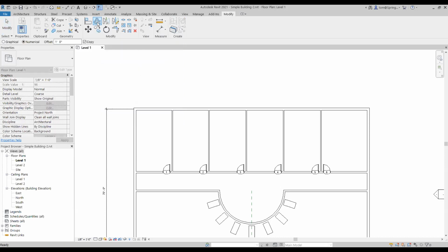And once we start the offset command, we're going to use an offset distance here. So under offset distance, we're going to change it to 14 for 14 feet. Hit our enter key. So now my offset distance is 14. So I started my offset command, I made it 14, and I'm going to make a copy here. I'm going to go ahead and select the top horizontal wall. Now watch this. I'm going to touch it here. You'll notice it can go up or it can go down. I want to make sure it's going to go down. So I'm going to hover my cursor here so it goes down. I'm going to click. And boom, it's going to give me that wall right there. So I went ahead and offset that.